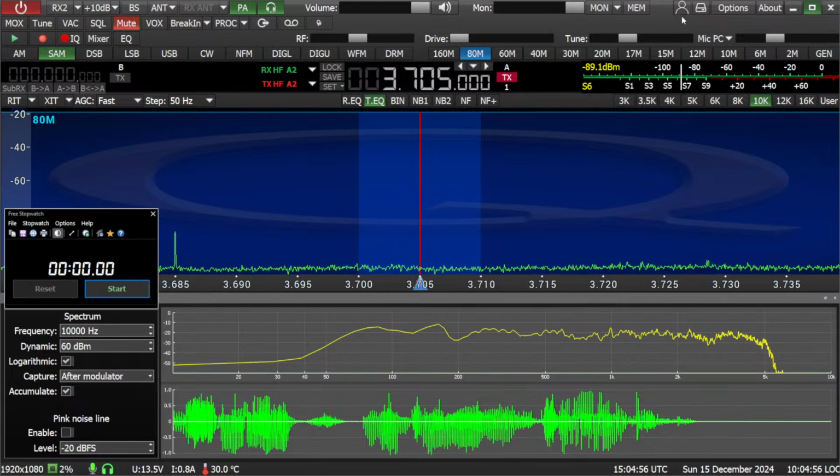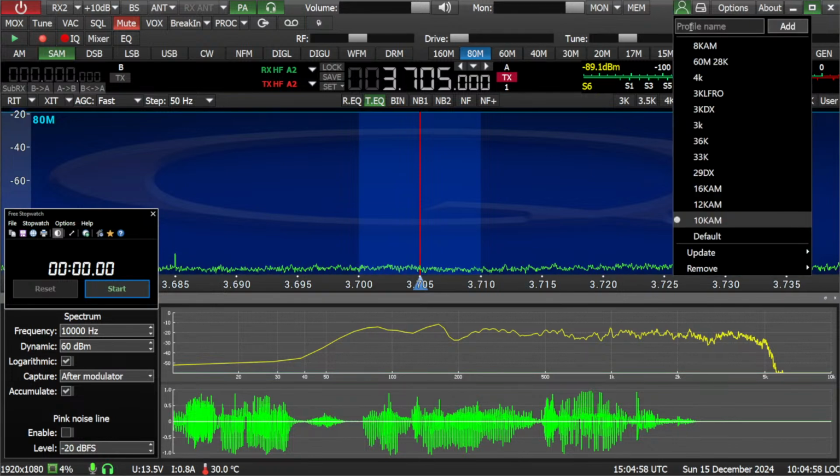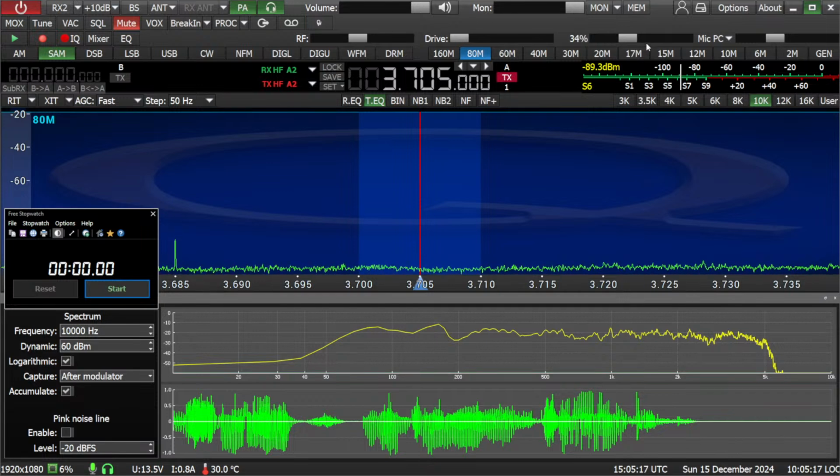Then you can put your profile name in. Don't use strokes, dashes, dots, anything. It will not save the name. It screws it all up. So I put in 10K AM as the profile name, hit add, boom, that's done.